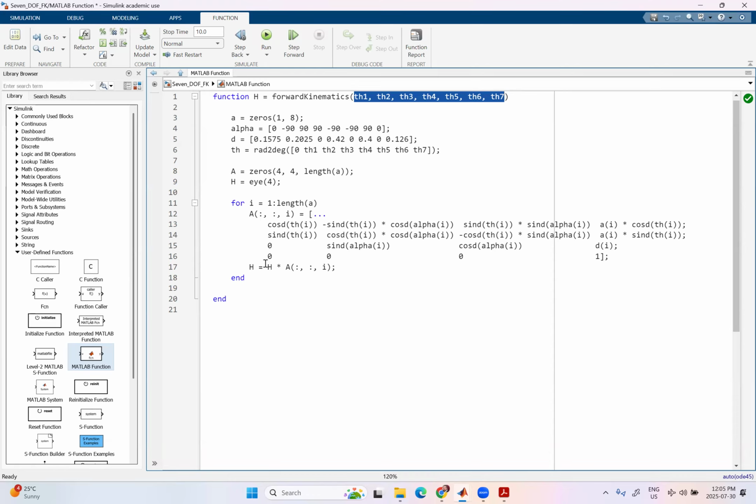That matrix is a homogeneous transform matrix. Let's not forget forward kinematics. What did we used to do? We used to multiply all the transforms from link 0 to 1, 1 to 2, and then we would find a transform from link 0 all the way to the end effector. Do you remember that? T from 0 to the end effector. So this at the end gives us that multiplication and so on. As you can see, all the multiplications in loops are being done. It's another way of generating a forward kinematics matrix transform. So we have done that.